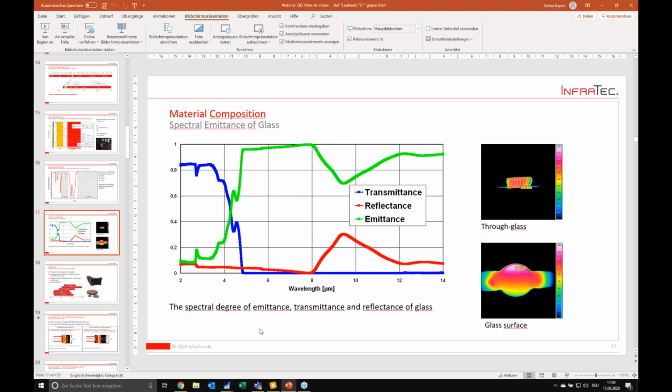So it really depends on what material you have in your existing measurement chamber or viewport or whatever, and you have to maybe ask the manufacturer to give you a spectrum, and then look for a good transparency in the IR wavelength band in general, and then you can choose your IR camera from this.